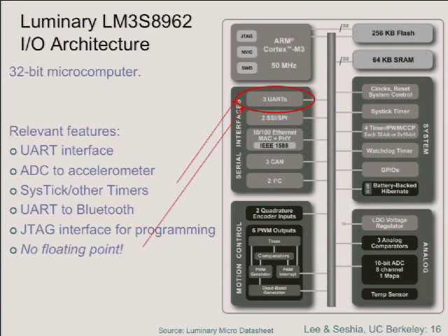And so you've done some multi-threaded programming. Threading is a concept that doesn't exist in hardware. It's a conceptual model on top of what the hardware does. The hardware gives you concurrency by one of two mechanisms today. Either you have two distinct processors, and they're running instructions sequentially. That's a multi-core architecture, or you're using interrupts.